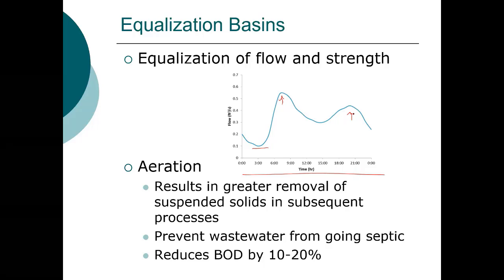Now, equalization also attempts to equalize the strength of the waste because your BOD levels will be an inverse of this. So if we look at BOD as a measure of strength, it typically will be the exact opposite. So the highest strength in the middle of the night, lowest strength in the morning, and then some oscillation during the day.